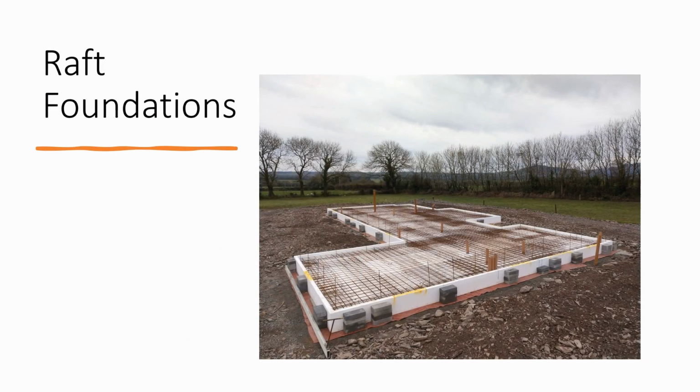Next is the raft foundation, and this is a reinforced concrete slab under the whole of a building or extension. It looks like it's floating on the ground as a raft floats on water. This type of foundation spreads the load of the building over a larger area than other foundations, lowering the pressure on the ground. This is an alternative if you can't use the traditional strip or trench fill foundations, but it's important to note that raft foundations aren't suitable in all cases and usually need to be designed by a structural engineer.